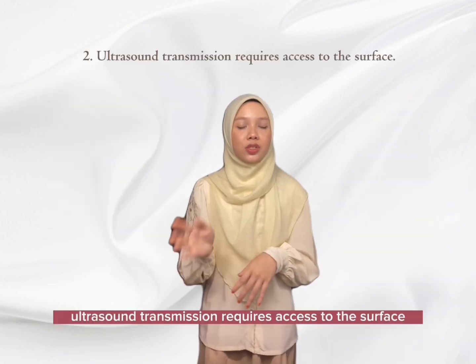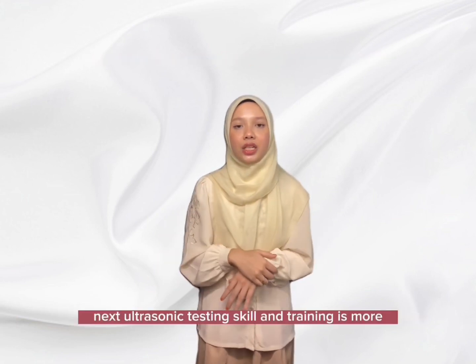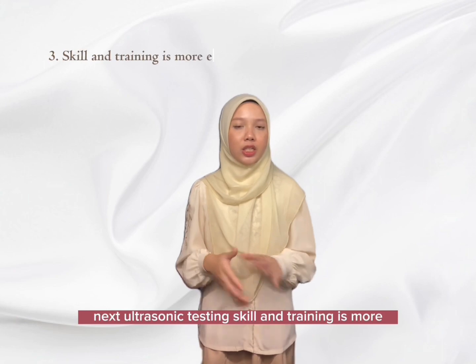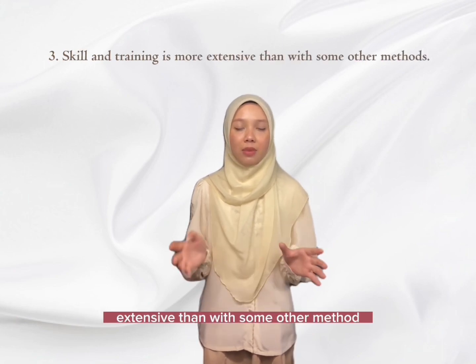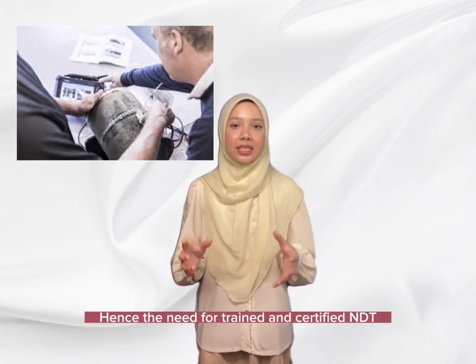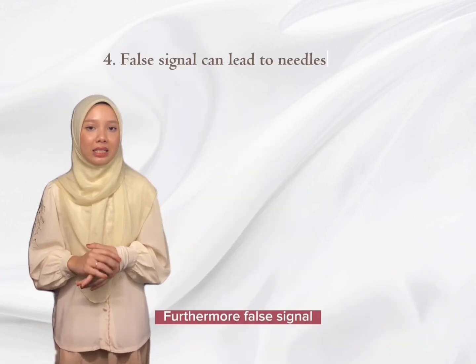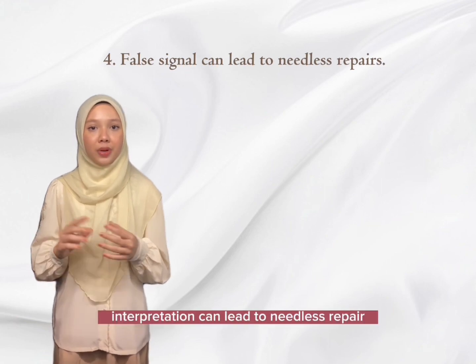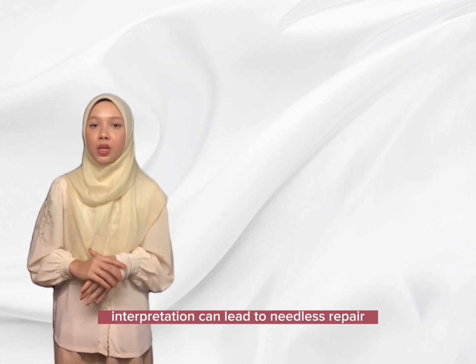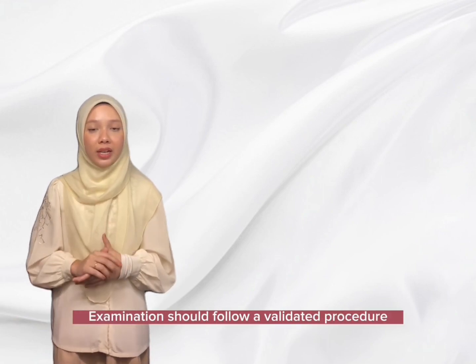Following that, the ultrasound transmitter requires access to the surface. Next, ultrasonic testing skill and training is more extensive than with some other methods. A high degree of operator skill and integrity is needed, hence the need for trained and certified personnel. Furthermore, false signals and incorrect signal interpretation can lead to needless repair, which is why any ultrasonic examination should follow a validated procedure.